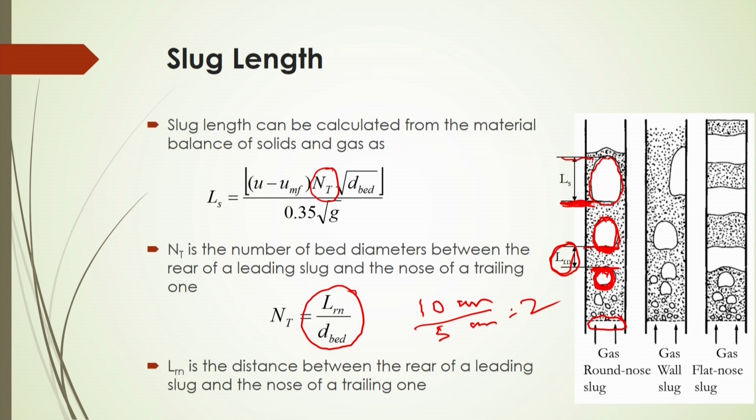Of course, the main factor is the gas velocity. So, at a certain gas velocity, for example if you are taking the minimum slug velocity, what you have to do is take a snapshot of those slugs by a high speed camera, and then calibrate with a certain distance or actual length by marking it before taking the snapshot, using a scale.